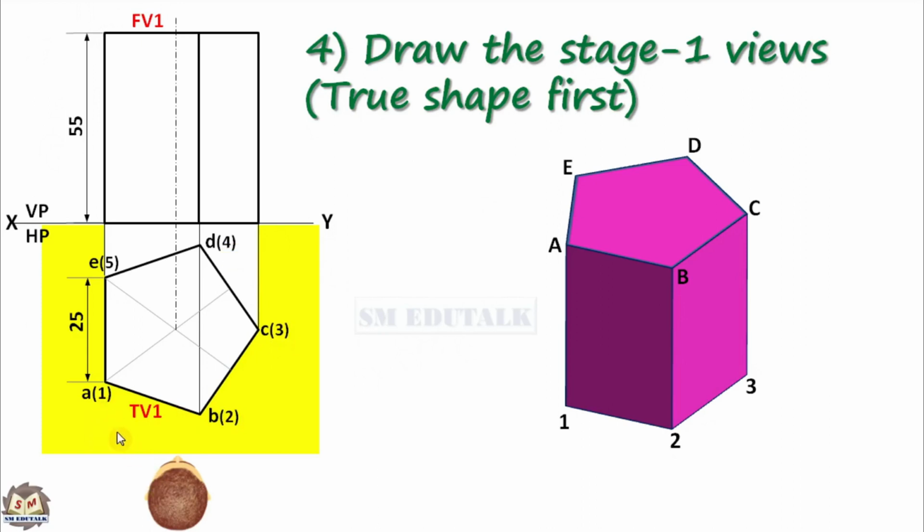So here he can see the point 1, but he can't see the point 5. Here also you can see 1 but you can't see 5. So this corner is named as 1 dash bracket 5 dash. Similarly, he can see the point 2 and point 4 is right behind point 2. That's why this point can be written as 2 dash bracket 4 dash. And here only one point is there, that is point 3. It should be written as 3 dash. And the top base is named by alphabets. So he can see A but he can't see E.